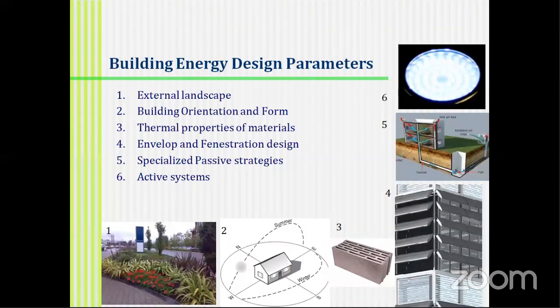Orientation of the building, the form of the building, is again very important with respect to the sun path, how you actually place your building, which are the facades that are exposed to maximum heat, and how through design we can have buffering within for effective climate control in buildings. And the forms, what are the better forms? Do we have long buildings, small buildings, round buildings, tall buildings? So all of these are very effective.